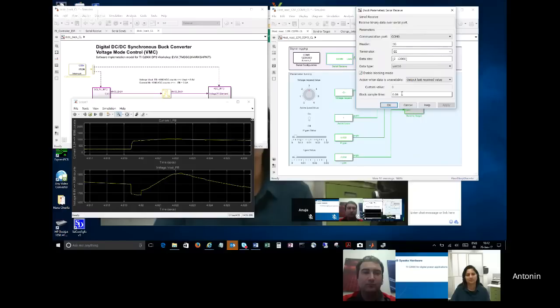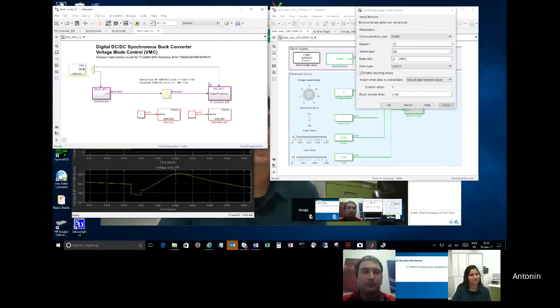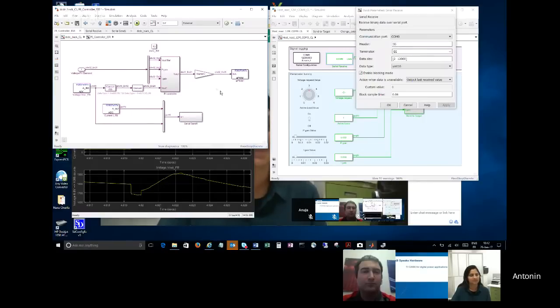And Simulink is pretty good at dealing with big chunks of data at slow rate, whereas your microcontroller is pretty good at dealing with small chunks of data at fast rate. So if I can use that segue to jump into what's happening on the target, I can start with the communication channel. So basically, I have an interrupt here that triggers my PID control loop, and I'll show how this interrupt is generated. And here you can see the serial send. So this interrupt, you'd have to trust me now, but I'll show you that it's triggered at 200 kilohertz. So I read 2 ADC channels every 5 microseconds, and I do a serial send.